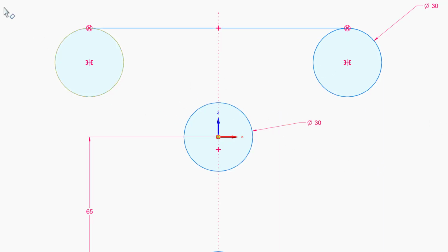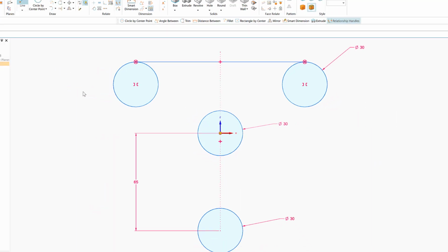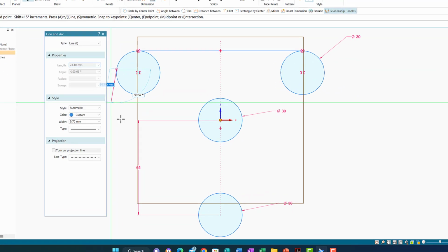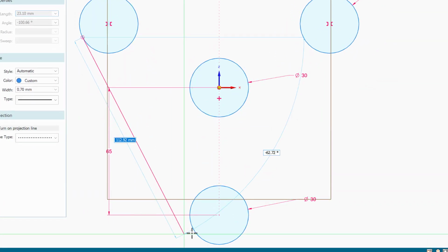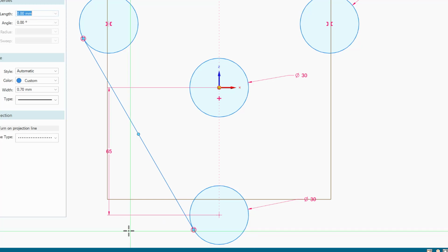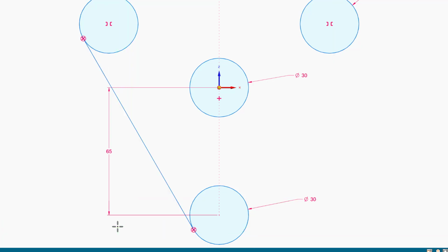Now we're going to repeat the same process on the other sides. I'm going to click at any point here, move it, and come tangent to this circle. When I see the two symbols, I click, right click to get out, and escape, and I should see the circle with an X. Let's go to the other side.